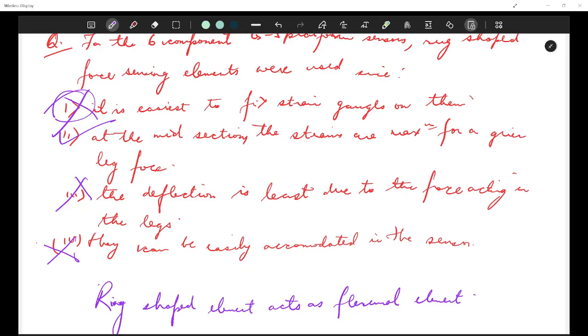In the Stewart platform force torque sensor, external force is measured by the leg axial force, which is transformed to it, and the leg axial force gives us the strain, and strain is the electrical signal. We want pure force transmission, we want no energy loss, we want no hysteresis and no nonlinear effect. So the correct option is kinematic joints have friction, which results in inaccurate measurement, which was the first option. And the reason is normal joints have friction, they have backlash, they have the static friction, and they have hysteresis.